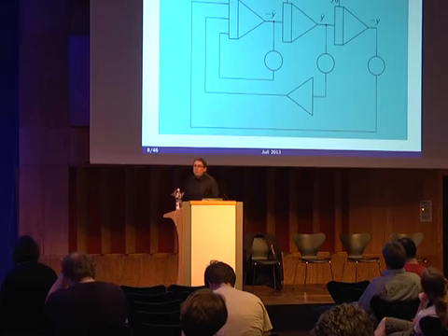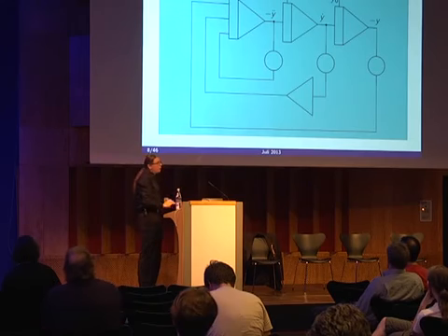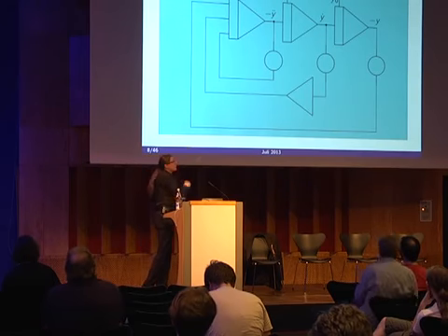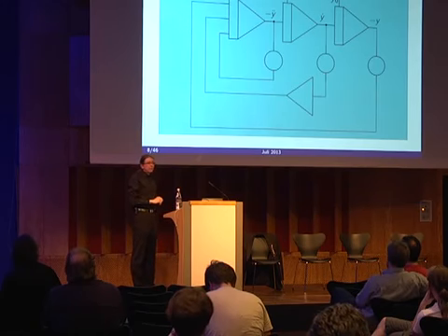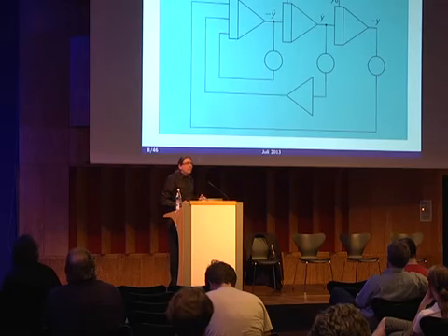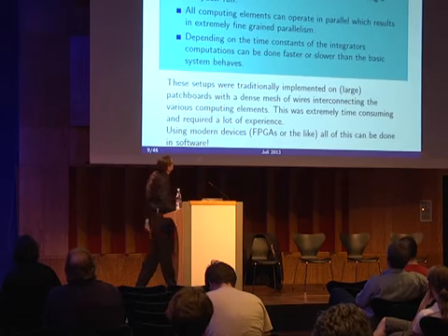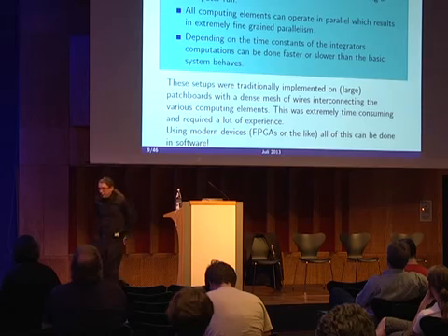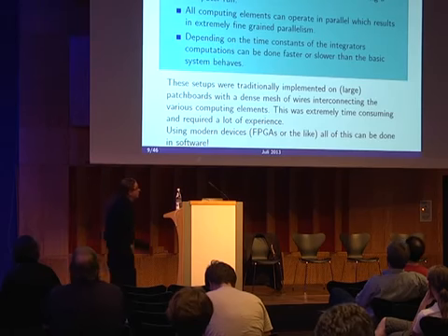Regardless of how you implement your integrators, your summers, your coefficient potentiometers, which are represented by these circles, you can program a machine by diagrams like these, because these diagrams describe the structure of the machine, which will be an analog, a model for the problem you want to solve. That's just a very, very simple example, but I hope you got an idea how an analog computer is programmed. There's much more to it.